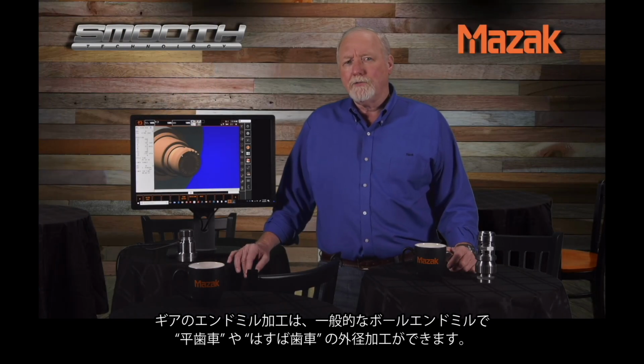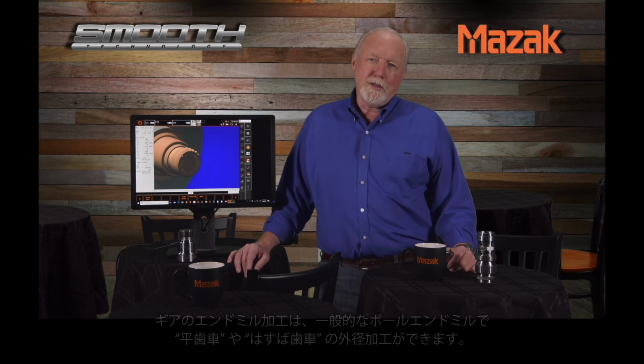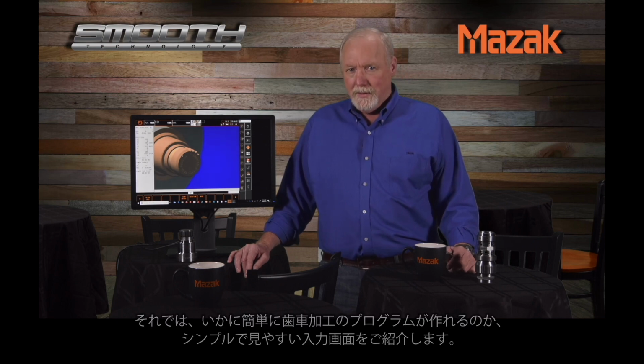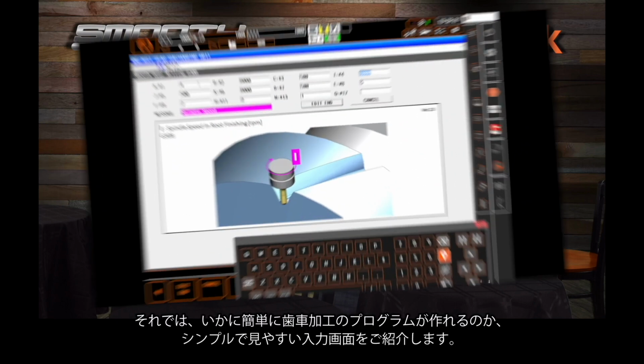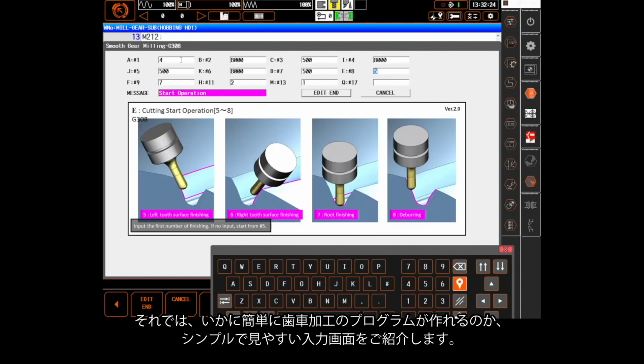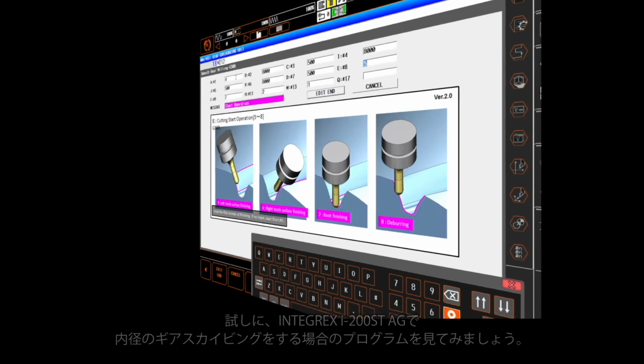G304 to 308 are for gear milling. Gear milling is for using a standard ball end mill for most external spur and helical gears. The graphical nature of the SmoothX control allows for custom graphical input screens, greatly simplifying the use of these functions.